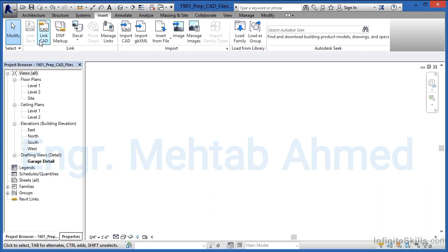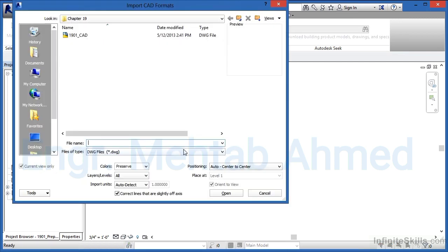The nice thing about doing that with the link is that you know you get all the lengths exactly right. You don't have to do much measuring. It's just click, click, click, click, click, and fill in the information without having to be amazingly accurate because the accuracy is already drawn for you inside of the original CAD detail. Now, the other thing that you could do instead of linking it in and then being forced to just trace over the top of it is you can import the CAD information in.